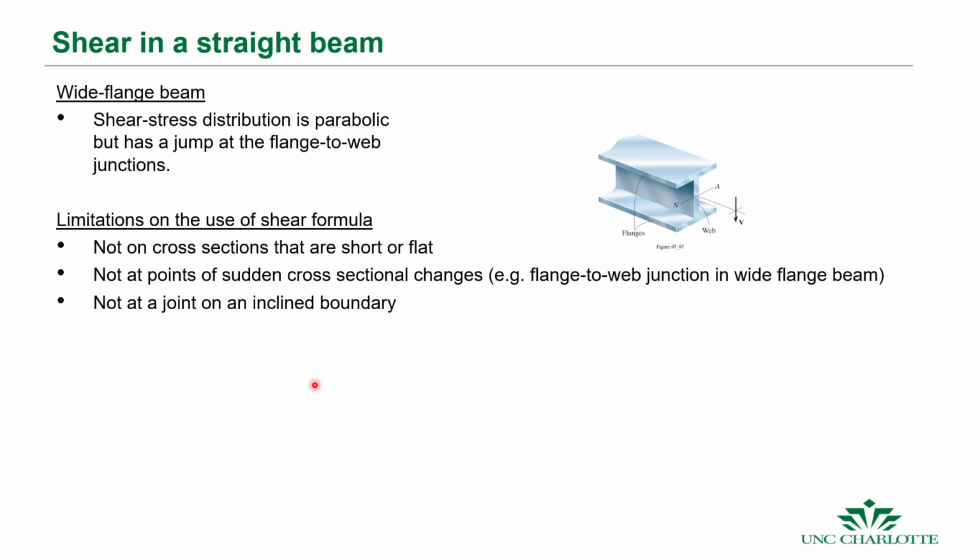We often have wide flange beams where we put the mass far away from this axis. Okay, the farther that we put mass away from an axis that runs perpendicular, the greater the moment of inertia is, and the moment of inertia is the measure of the resistance to bending. So if we want to resist bending, we should move the area as far away from that axis as possible. So that's why I-beams are shaped the way that they are.